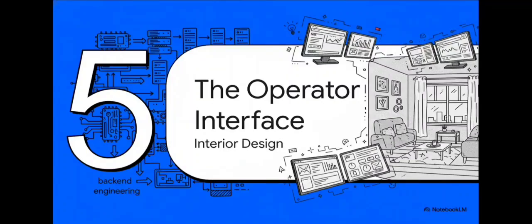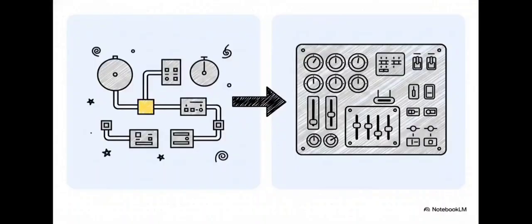Section 5. The Operator Interface. Okay, stepping out of the back-end engineering for a second, let's talk about the interior design, the actual interface the operator is going to rely on every single day. There's a crucial distinction here in how operators interact with the system. On one side, you have block icons. These are your high-level, at-a-glance dashboard indicators embedded directly into the plant visual. On the other side, you have faceplates. These are the detailed, separate pop-up windows that you open up when you actually need to change a set point or alter an operating state.